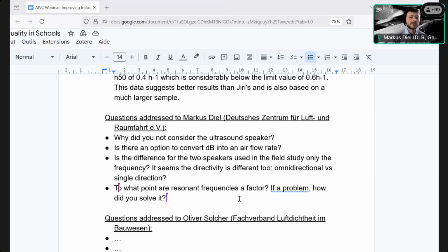And also, we tried doing some airtightness measurements with a blower door while doing it. The problem is that the blower door is quite loud, and so it has more of an interference effect with our measurement than it does help it. So no, there's no difference between doing 50 pascals or 150 pascals overpressurization inside.